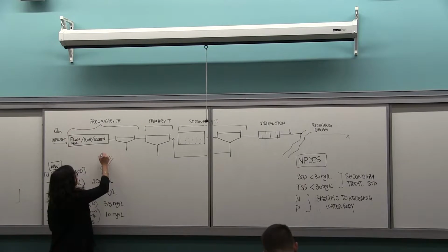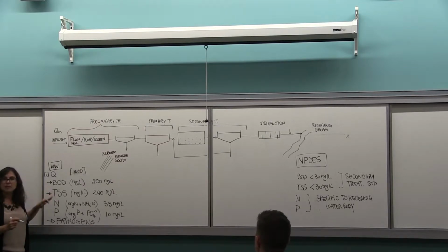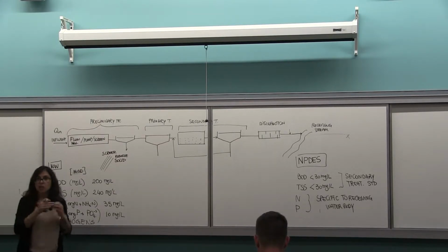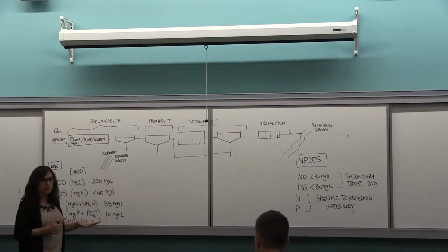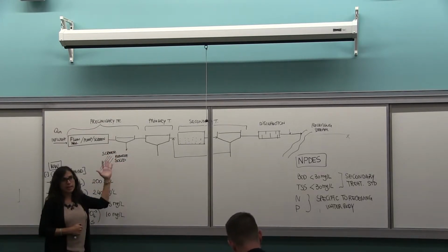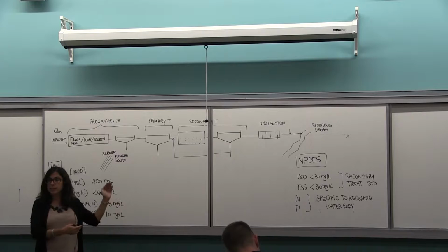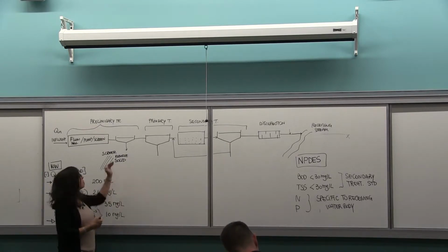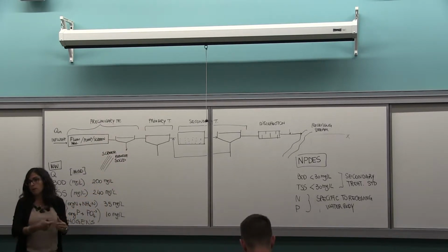So the screen is to remove solids. But the solids here are not the suspended solids, the fine solids, but the large ones that can be removed in a screen. When we talk about suspended solids, we're talking about the micron range. Here we remove settleable and large solids like rags and stuff that could be present in the sewer line, and sand, which can also affect the lifetime of your pump impeller.